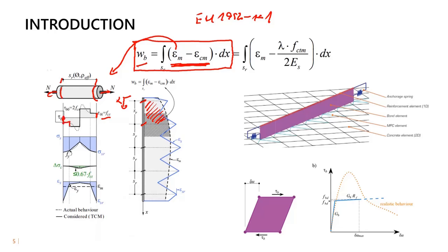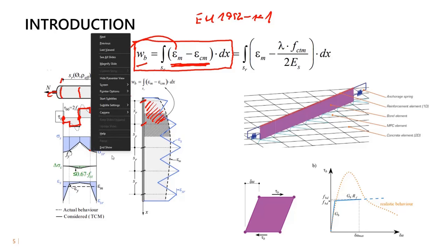In between the cracks, if we make it uniform over some regions, we can see that the bond stress is increasing towards the middle point in between the crack spacing. This means the biggest bond is in between the cracks, and the bond is dropping down after you reach the yield point.